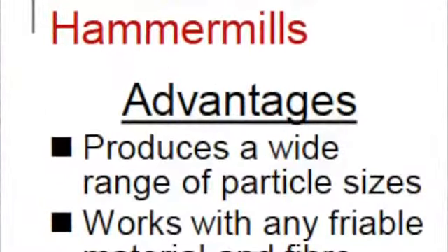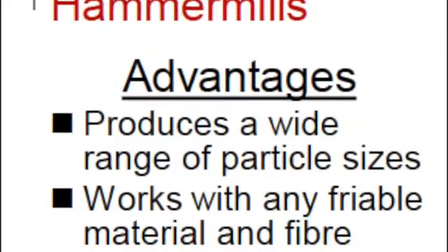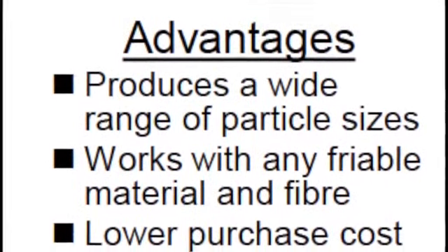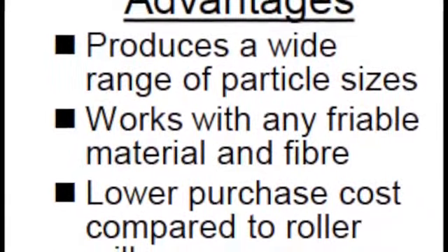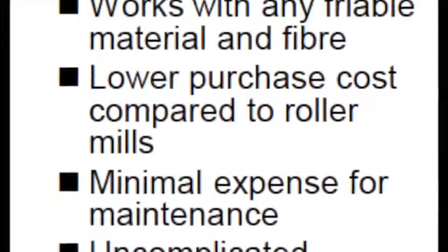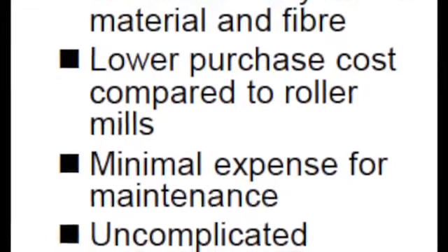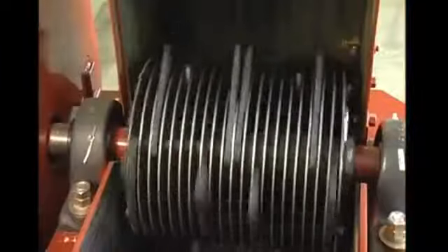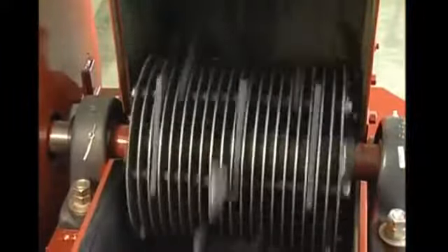From the information summarized in this report, we have concluded that a hammer mill is the best choice for grinding commodities in preparation for extruding pet foods. Hammer mills can produce many different particle sizes, can work with a wide range of ingredients, are a cheaper initial investment, have a cheaper and easier maintenance, and are less complicated to operate. Although roller mills are more efficient in energy savings, they are not able to grind to the particle size